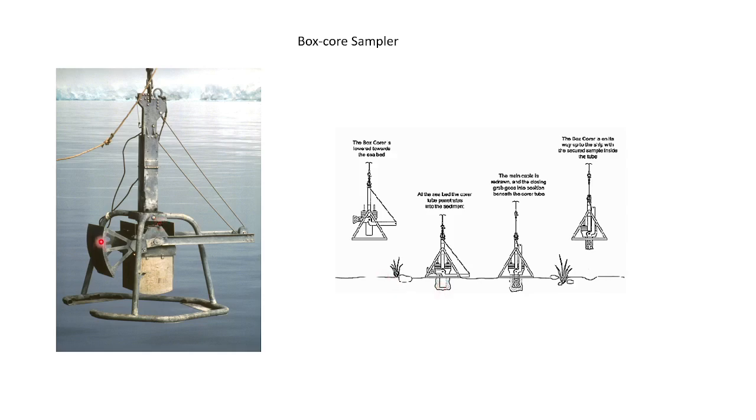See, this one is the cutting edge. First we'll keep it like this. Now if we loosen this string, which is called the draw wire, the cutting edge will come like this, and then it will cut the sample, and it will get contained in the box, because first the box will penetrate.